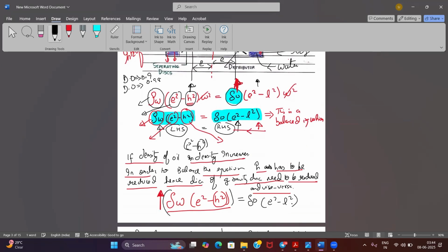So if the surveyor asks you what you will do in the purifier if the density of oil has increased, what you got in the bunker is more than the previous density, then you have to say that I will use a gravity disk with smaller internal diameter. This is what you have to say, and this is also vice versa. If he says the density has decreased, then you have to use a bigger internal diameter of the gravity disk.